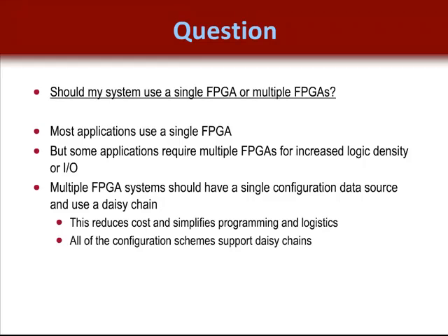Another common question is, should my system use a single FPGA or multiple FPGAs? Well, most applications need only one FPGA because the newest devices, of course, have very large density. But some require more pins than are available in a single package, or, again, more logic than they can possibly fit into the largest device.